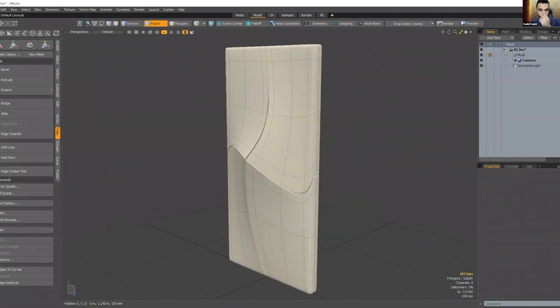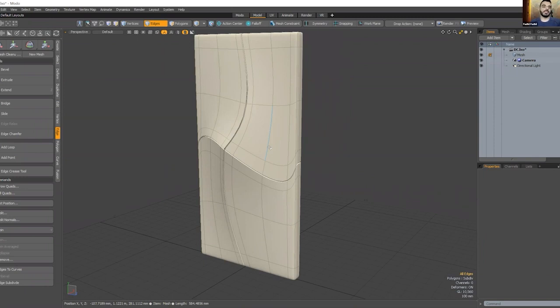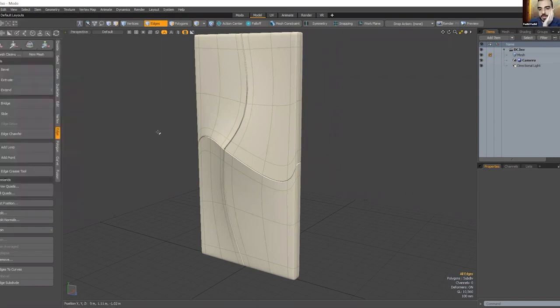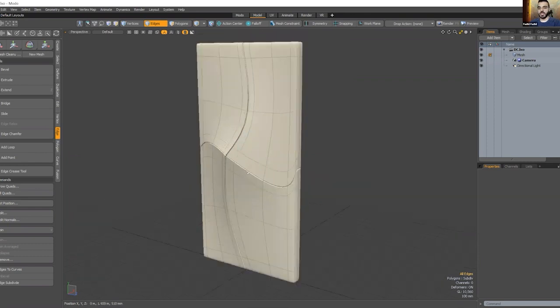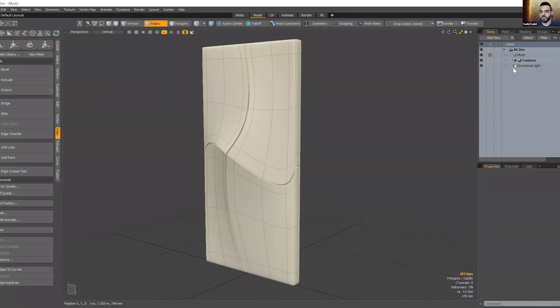And here we are. I think up to this point, we've only made simple changes to this, and it's sort of ready to have further articulation. In some cases, if you're working in an evolutionary way, where I am starting from a simple geometry and then you move to the next one, you get to a point where you have some results that you would like to keep, so you don't want to save over it. You have the option to create another mesh and keep adding copies.